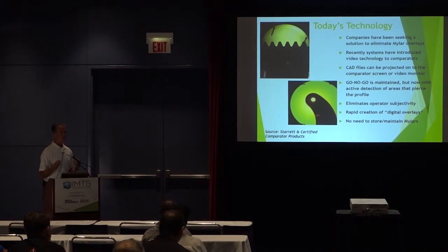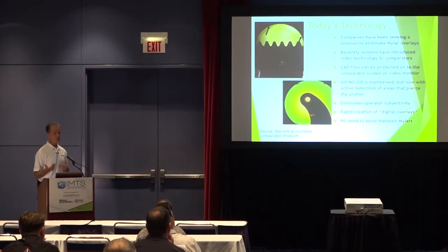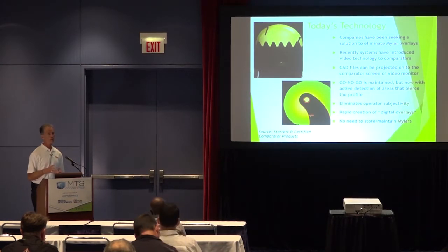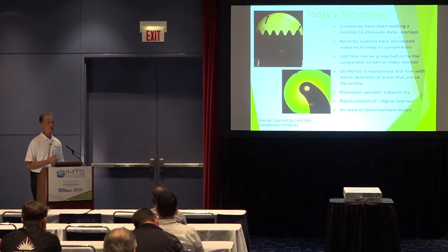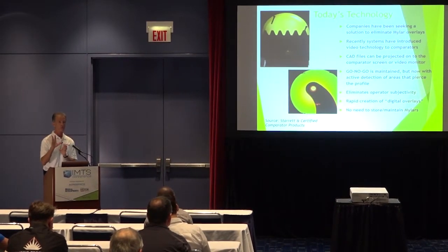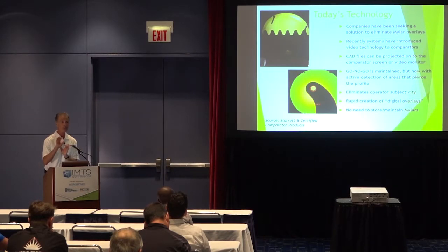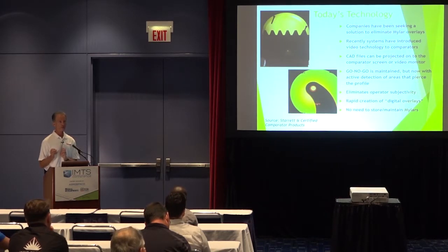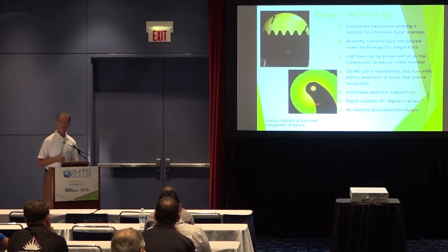So what has happened over the past few years is the advent of using the DXF file, the design file, to actually project that onto the screen to compare the actual part. So now we're not relying on that overlay, and if you've ever used an overlay, sometimes it's very, very hard to determine where something's in or out. It's just a subjectivity, it's a trained operator. So the DXF file gets rid of the Mylar overlay and gives us more flexibility than just what the Mylar overlay gives us. So that eliminates that subjectivity, and we don't have to store and maintain Mylars anymore. So that helps the process move along, and it's a savings as well.